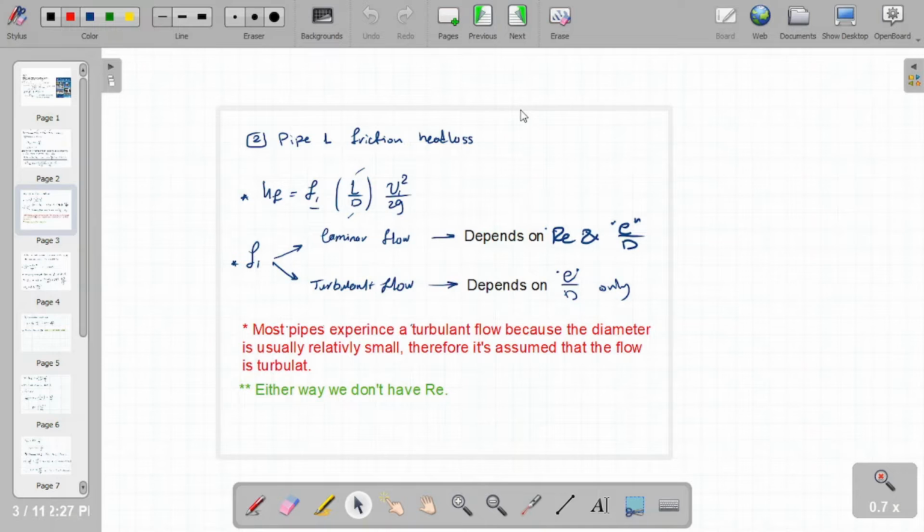So, in this equation, all the terms are actually known. We have the length, we have the diameter, but we don't have the velocity, and we don't have the gravity acceleration. But we can rewrite V1 in terms of V2, similar to what we did in the previous step. So that will solve it. And for F1, we don't know the friction coefficient.